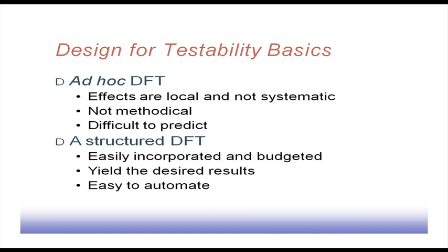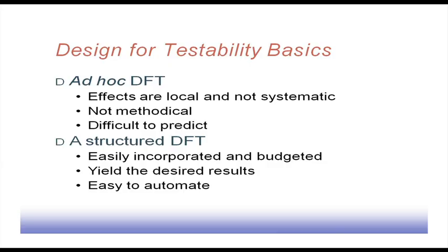As I said, this is totally ad hoc. Basically, the test engineer consults with the designer and says, can I introduce a line here, or can I introduce a multiplexer here, and if it is possible, then that is introduced. It is difficult to predict how much the benefit will be, because some points we may not be able to modify. So, that is the problem with ad hoc DFT.